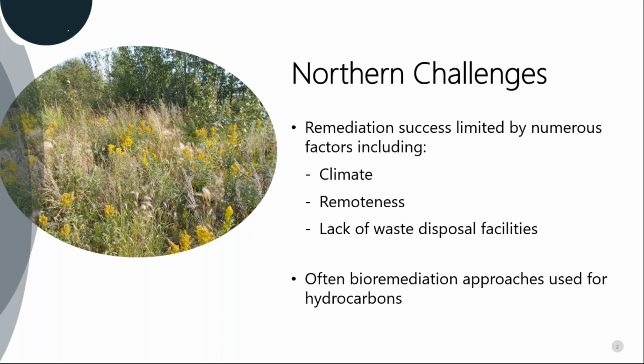most obvious. It's a very short field season up there with colder temperatures that slow down degradation processes, as well as the remoteness. The remoteness makes it difficult to get heavy machinery up there, as well as people, and there is definitely a lack of waste disposal facilities, all making it very expensive to do remediation work in the north. That being said, because of all this, bioremediation is often a good approach used up in the north.